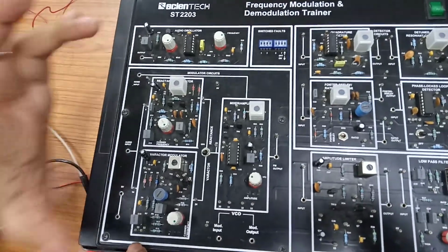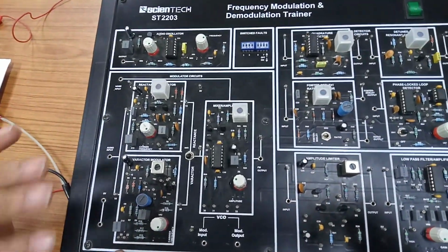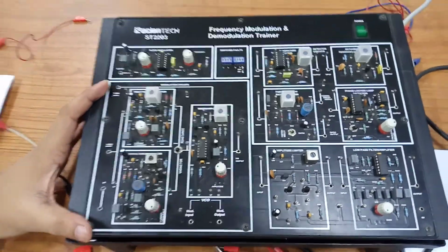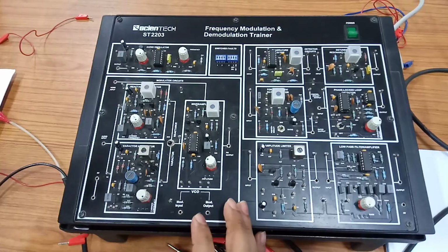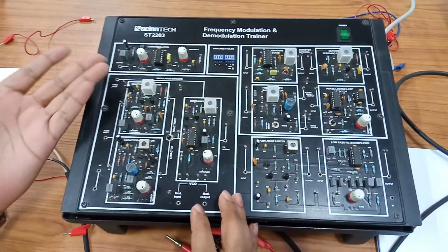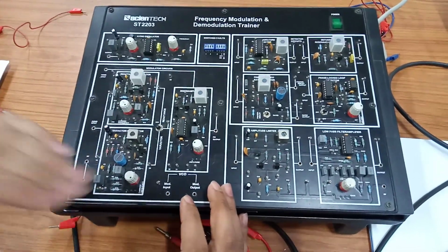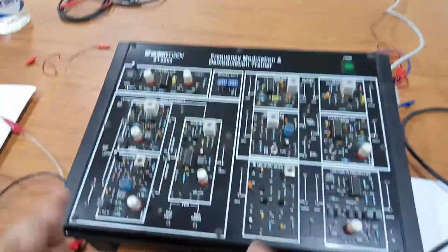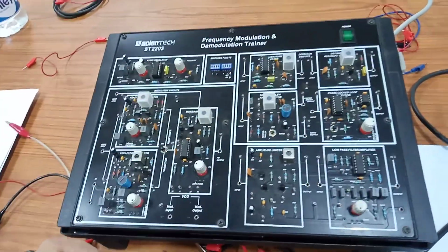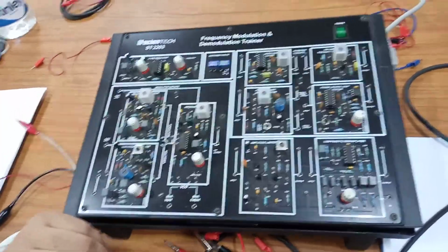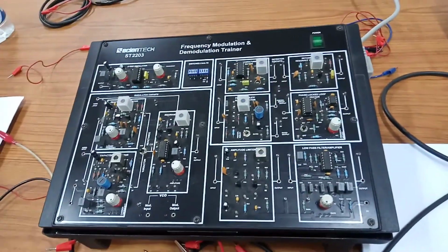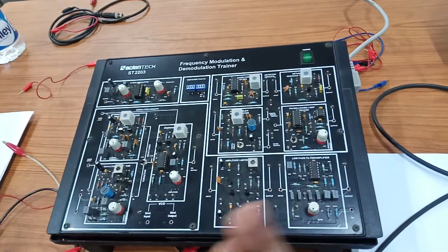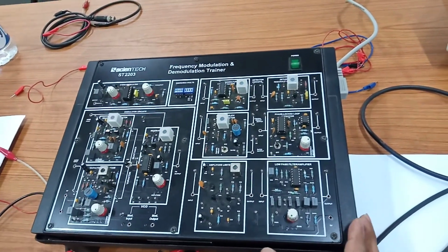When we are doing frequency modulation, as per the instantaneous value or amplitude of the modulating signal, the instantaneous frequency of the carrier wave is going to change. We are going to consider a sinusoidal signal of audio frequency. Wherever the amplitude is maximum, the frequency of the modulated wave will be maximum at that point. At the lowest part of the modulating wave, where the amplitude is minus VPP, the frequency of the modulated wave will be minimum. We'll see how the modulated wave looks.